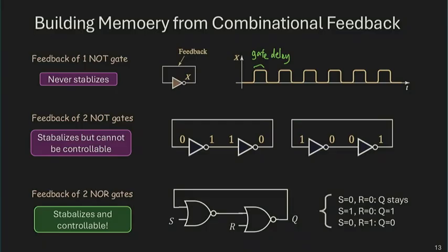It's going to settle down in one of those two conditions, depending on the initial condition, when you just turn on the power. You connect the device to a battery. All of these devices will receive some arbitrary initial value. And depending on what happened, which is out of our control, it will settle down to one of these two conditions. So it stabilizes, but you have no way of controlling the value.